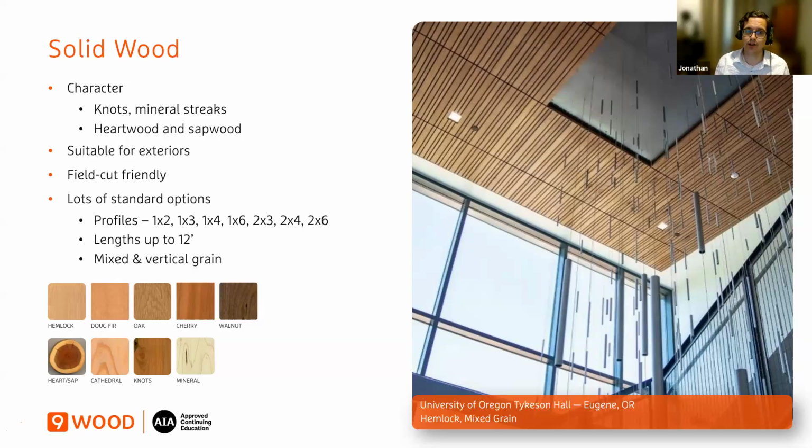The other benefit of solid wood is it's suitable for exteriors. Each manufacturer will have their go-to solid wood species for exterior situations, so you can deliver more longevity in those exterior applications for your client. It's field cut friendly. Veneers can be field cut, but solid wood doesn't require any special end banding. The manufacturers can set up subs to make the field cut successfully and touch up any visible ends with a particular stain and/or finish. Most projects, due to schedule limitations, ultimately end up with a field cutting situation, which can be done successfully.